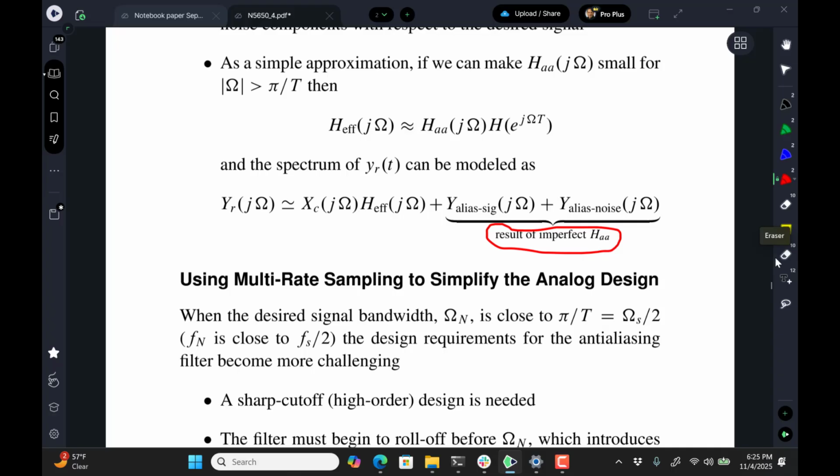I don't think my voice has too many overtones that are over 22.05 kilohertz. But even so, musical instruments like violins and flutes and other instruments that play in the treble clef, they can produce overtones up there. And if they were to fold in, you could all of a sudden start hearing them.